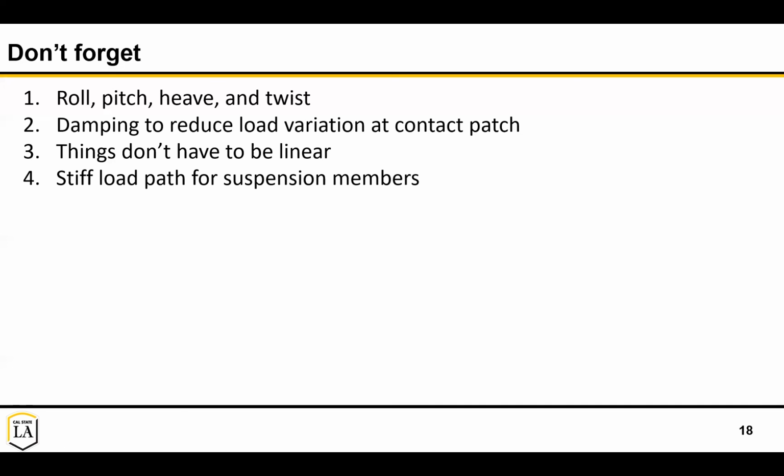That also includes things like your rods to control the toe, to have large moment arms and to be at right angles, so that you reduce the forces in those and the amount that they displace. Because keeping in mind that everything is a spring, and so there's compliance in the system that you might not be including, and there might be even compliances in the joints. And so once you get very stiff members, you'll find that the compliance in your joints might be dominant.